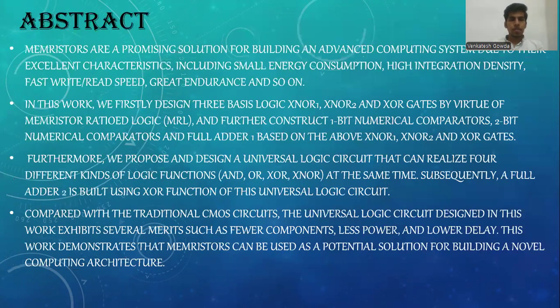So now let's get into the abstract part. Memristors are a promising solution for building an advanced computing system due to their excellent characteristics, including small energy consumption, high integration density, fast write-read speed, great endurance, and so on. In this work, we firstly designed three basic logic circuits such as XNOR 1, XNOR 2, and XOR gates by virtue of memristor ratioed logic, and further construct 1-bit numerical comparators, 2-bit numerical comparators, and full adder 1 based on the above XNOR 1, XNOR 2, and XOR gates.